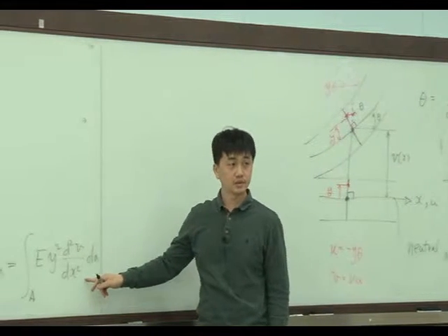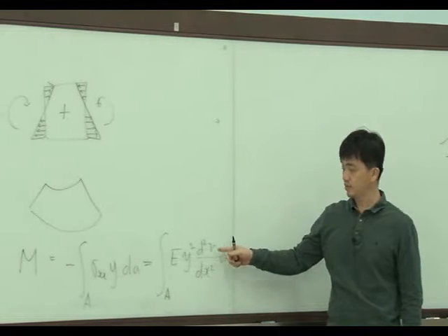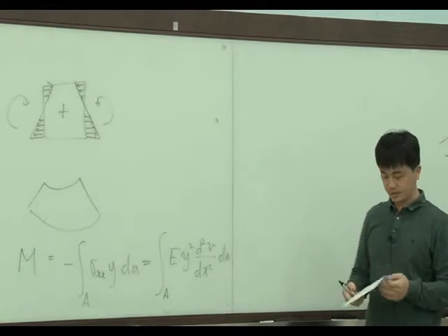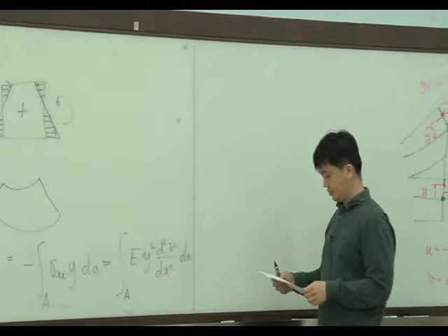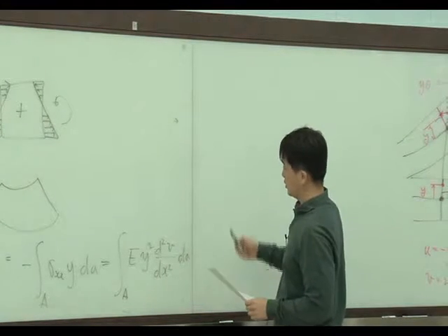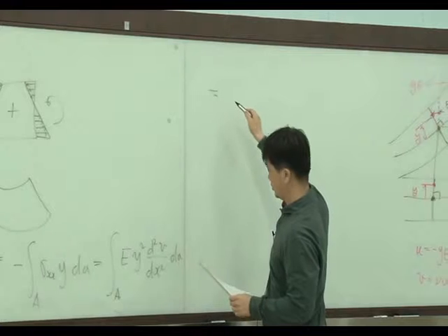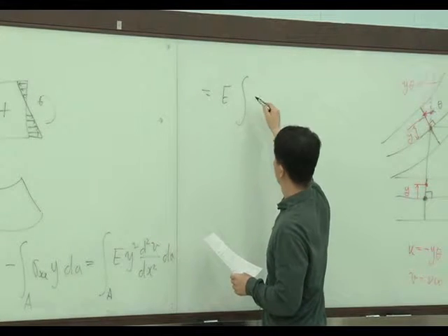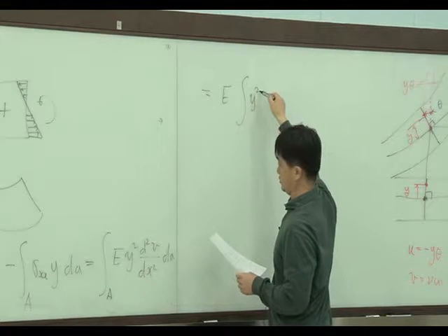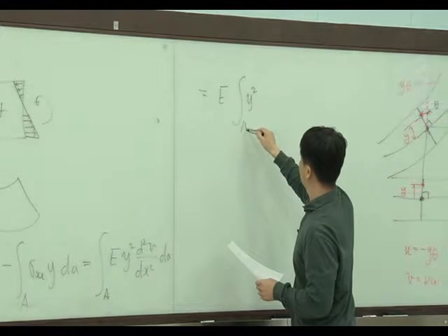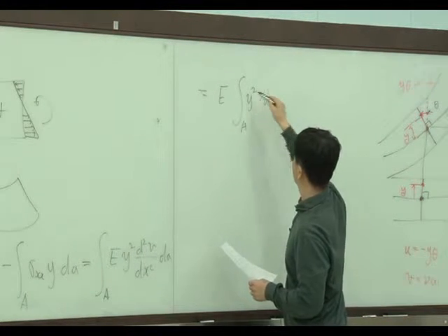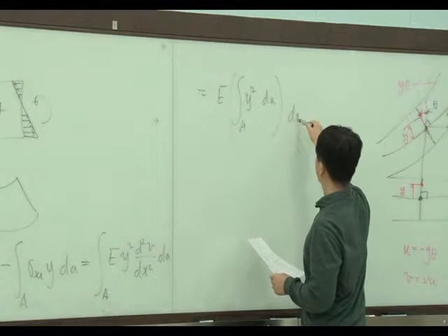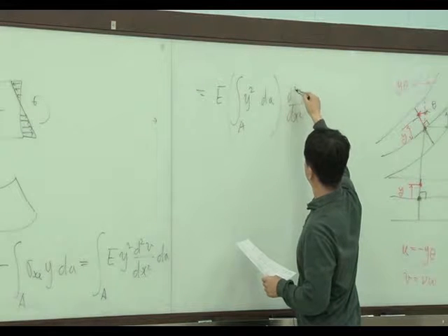Understand? So moment can be calculated from the transverse displacement, and that equation becomes E times the integral of y squared dA, times d2v/dx2.